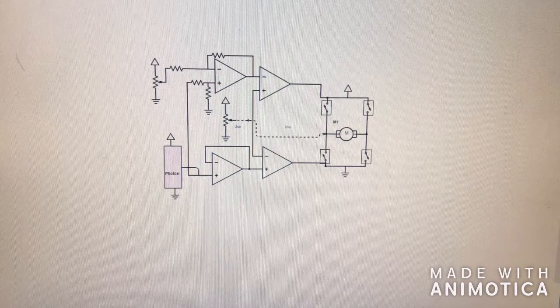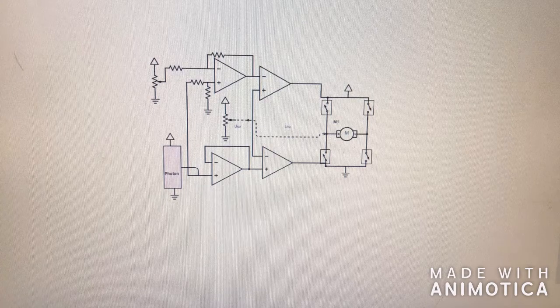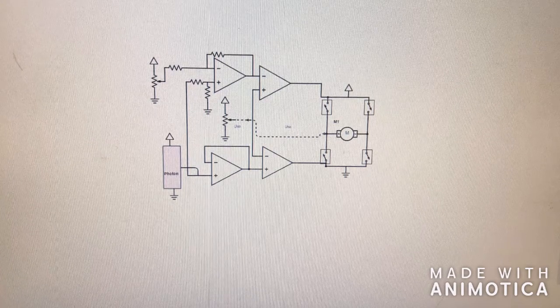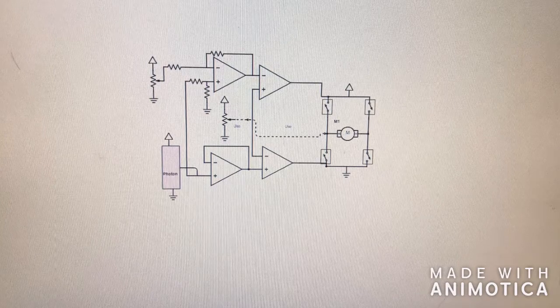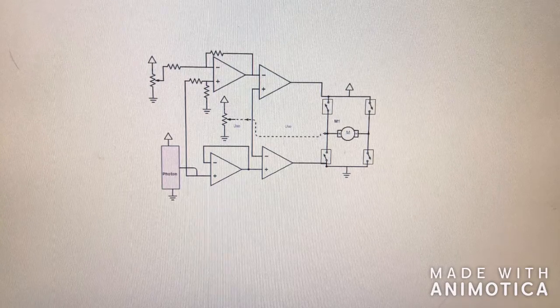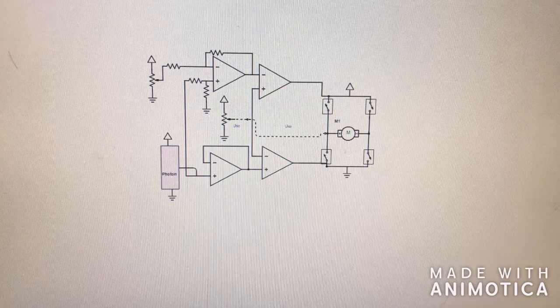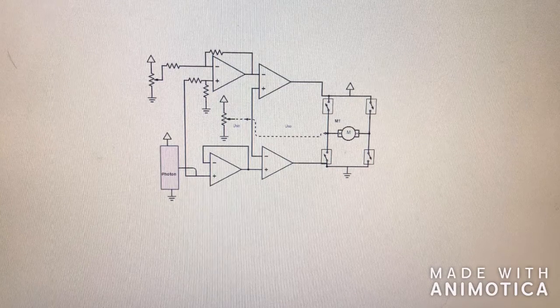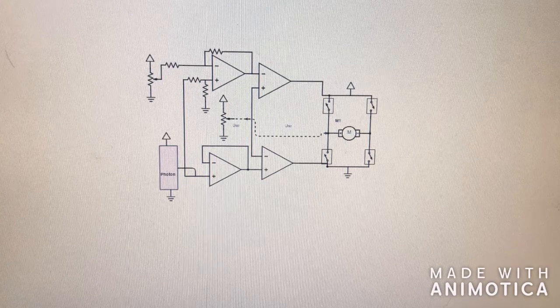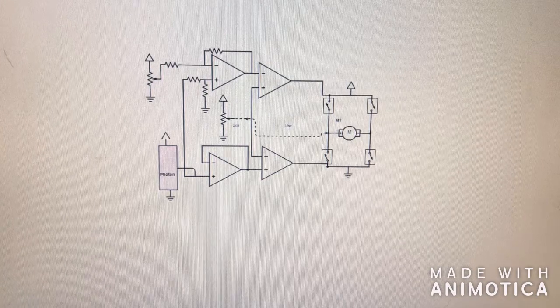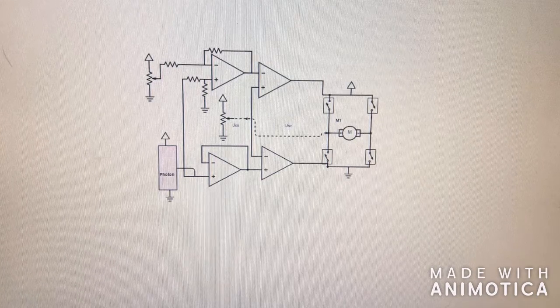Subsystem 2 uses the last 2 op-amps out of the LM324 package and takes the upper and lower limits that were established by Subsystem 1, in addition to the feedback, which will be talked about in the next subsystem, to determine if the system will run in forward or reverse. If the feedback is lower than the lower limit, it will send out a forward signal. If the feedback is higher than the upper limit, it will send out a reverse signal.